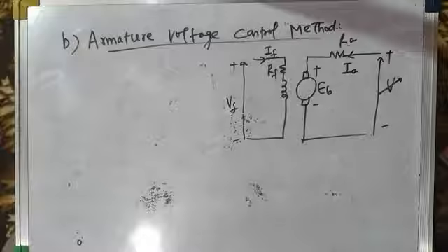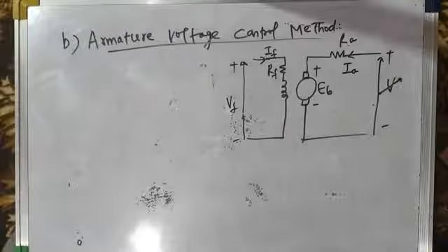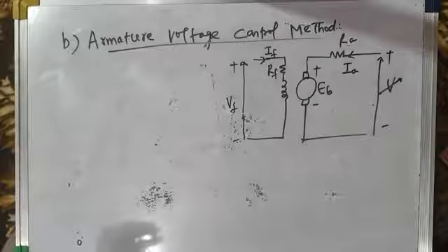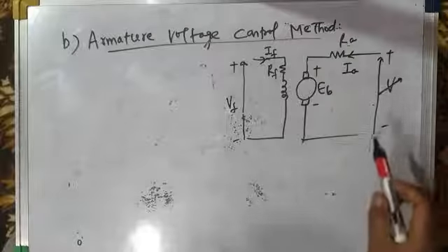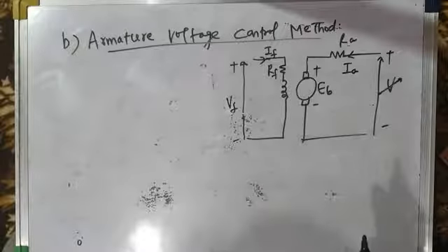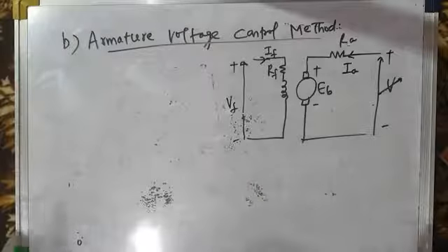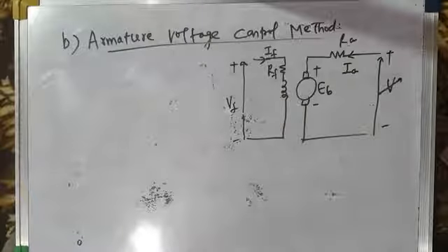That was one of the methods used for varying the armature voltage, but the method was highly bulky. It required large size. It was an inefficient method because for controlling one motor of say 100 horsepower you require two more motors of the same rating. So the total number of three motors, bulky, large size, large floor area, large noise level, and so on.